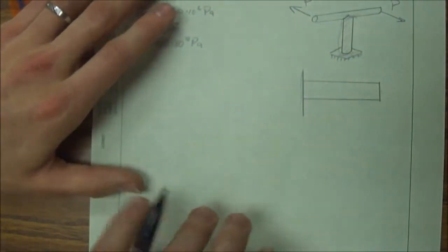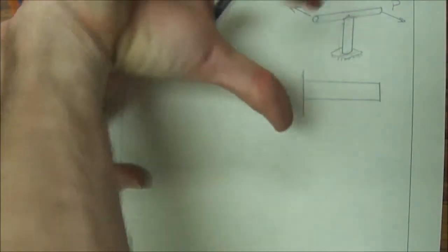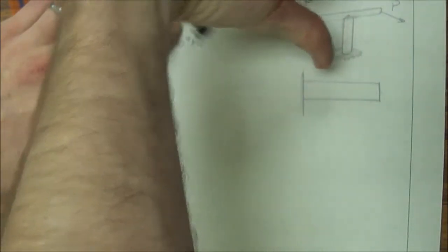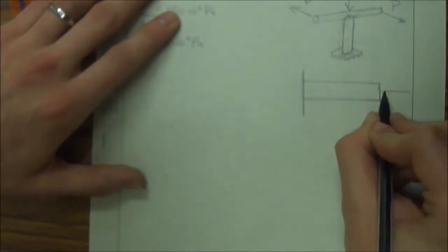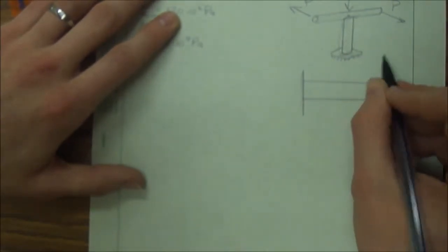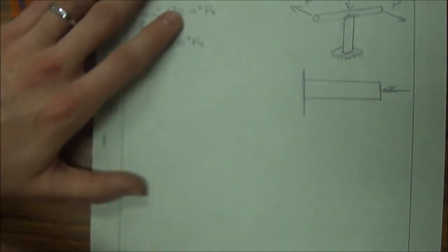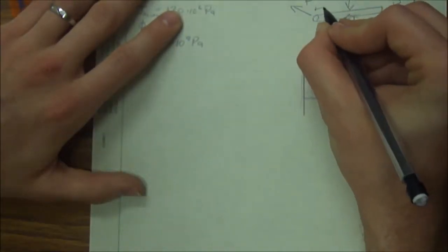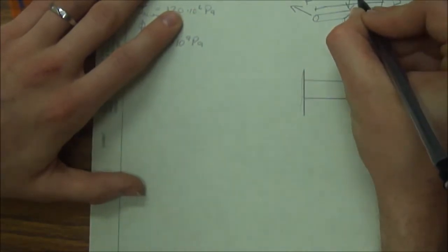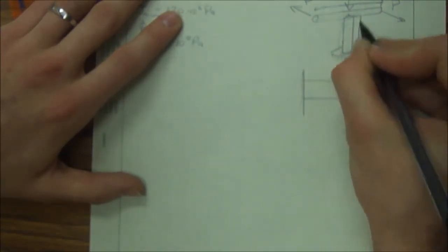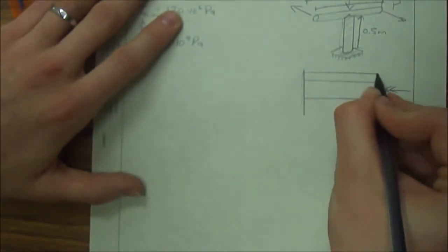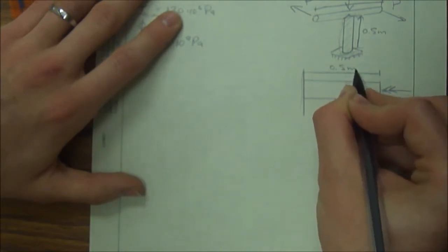Now I'm looking at this torque. According to my right hand rule, as I'm closing my hand, that's the direction P is pulling, and so the arrow would be down into this column here. And on our picture, I could write a double arrow. A couple other things I forgot to write on here is that this total distance across is 0.3 meters, and this is 0.5 meters tall. And on this picture, that would be 0.5 meters long.